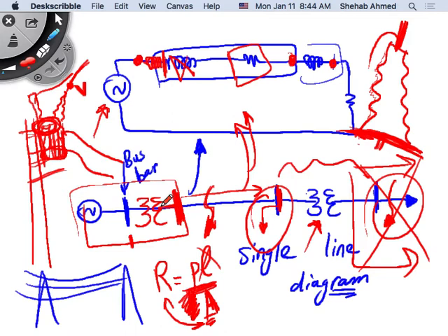We said we're making the transmission cables as large as possible so that they can withstand the current that's coming out, and we keep them spaced from each other so that we do not break down the air between them and cause an arc or flashover between the conductors. If you're transmitting 3 phases, we keep these large insulators and space them accordingly. If you drive from here to Al Khor or Ras Laffan, you will see these transmission towers with the cables spaced. They're not very close to each other, so that they don't flash over.